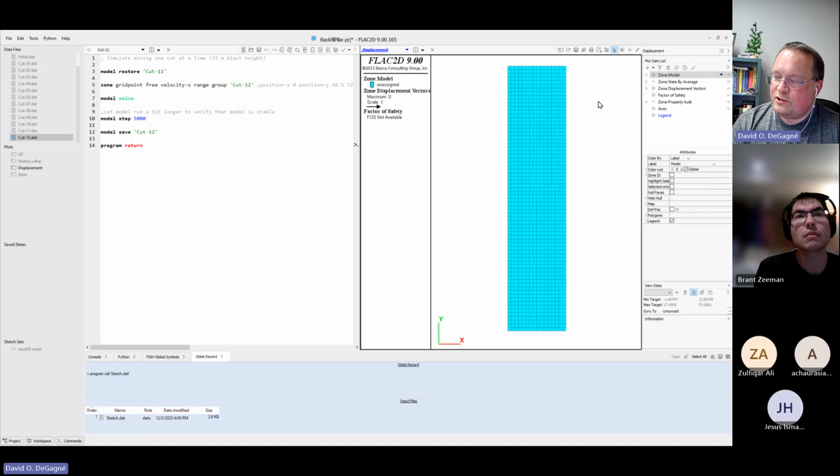It's a good way to make sure everything's behaving correctly by getting some feedback to make sure that you've correctly assigned values. So obviously, if you were to try to run the model at this point, you'd have problems because everything's undefined. And this is a way to check that the properties are available, or that the properties that you think are there, like a density of 2,700, are correct, and you didn't type in 270.